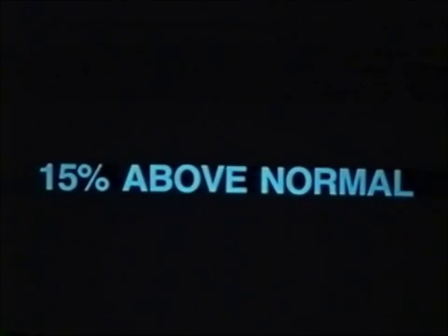This is 15% above the normal nameplate voltage for most single-phase equipment. For this reason, when using Y-connected units for both single and three-phase loads, you must make sure the line-to-neutral voltage is not too high for the connected load.